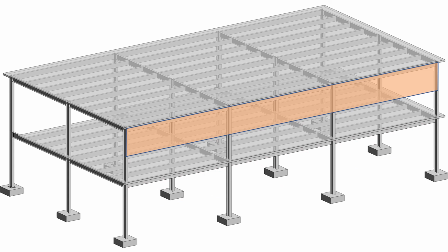Alternatively, we might look at the amount of force that's being introduced to the roof level of this building, where we look at the tributary area that's from the roof halfway down to the first floor level. We would take the tributary width or height in this case of that tributary area multiplied by our pressure loading, and then we would get a line loading in terms of W that would be pounds per linear foot or kips per linear foot.